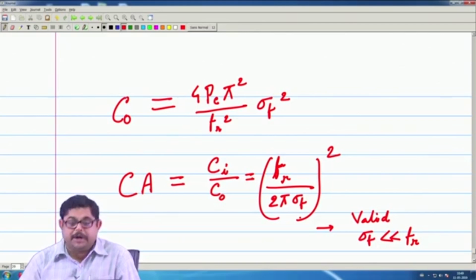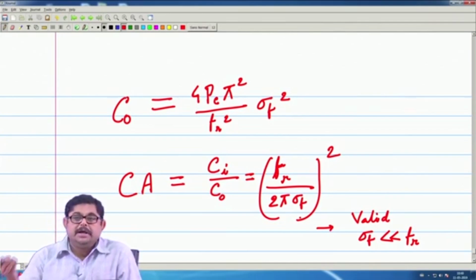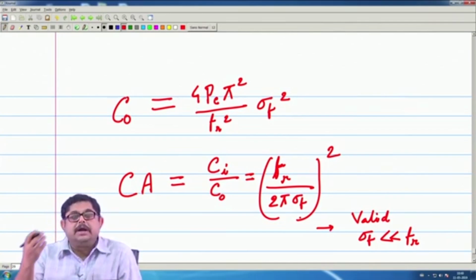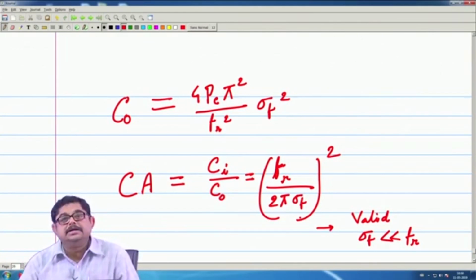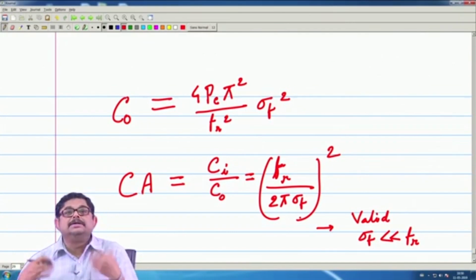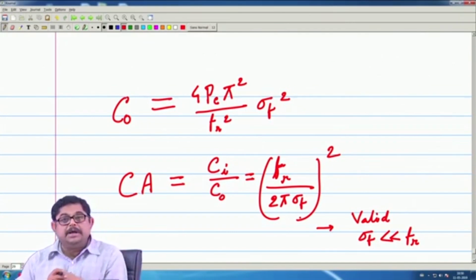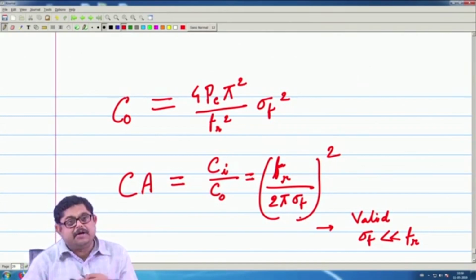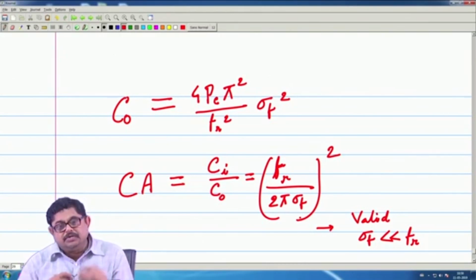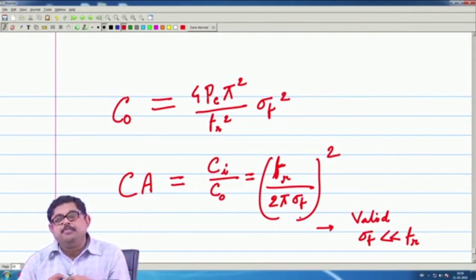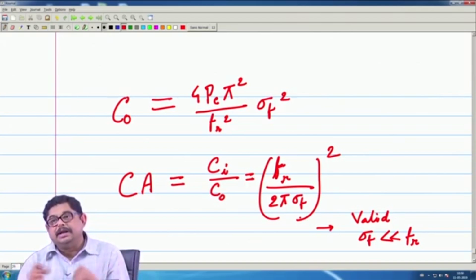That is more important, because clutter may be reduced, but if the signal to clutter ratio is not improved due to the MTI filter, then there is no point. So, that is the second metric, the MTI improvement factor, that takes care of that. Something like your noise figure in the case of noise. So, the corresponding thing in the MTI filter domain is called the MTI improvement factor. We will take up that in the next class. Thank you.